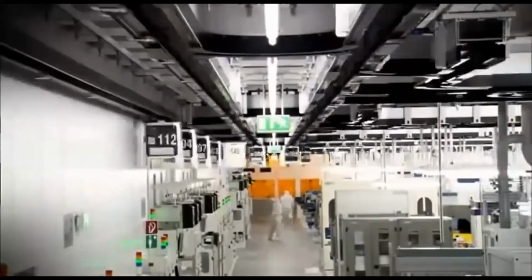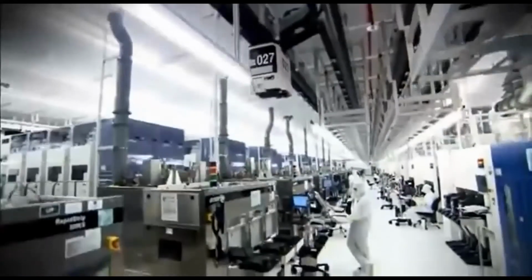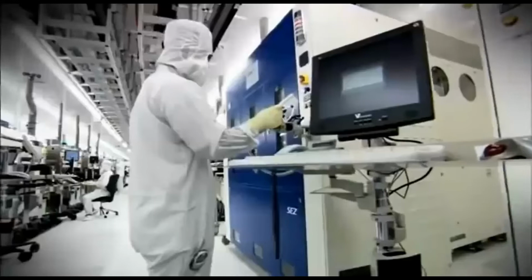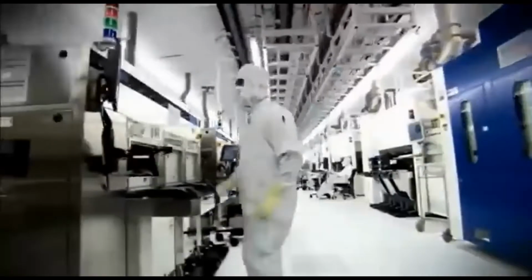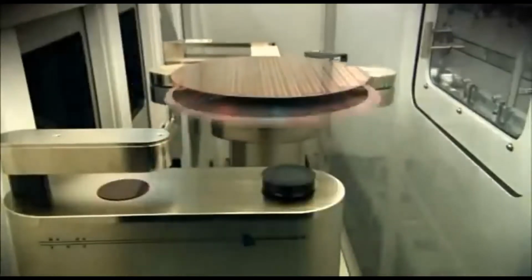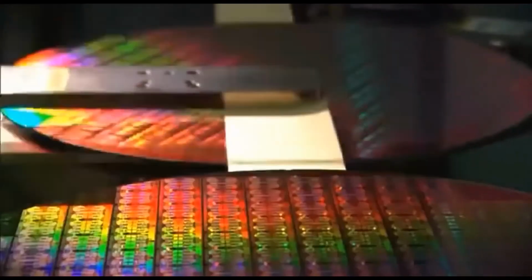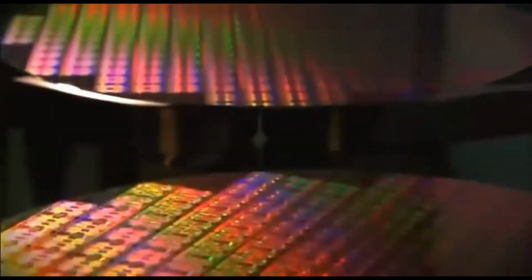From the photolithographic stage, wafers move on to ion implantation, where the electrical properties of the transistors will be specified. Here, the engineers make good use of one of silicon's most important properties. Silicon is a semiconductor, which means that its conductivity can be changed via a high-precision emplacement of so-called dopant atoms.